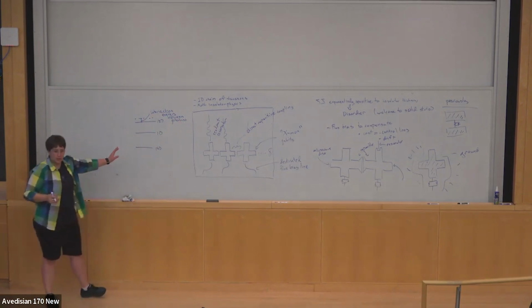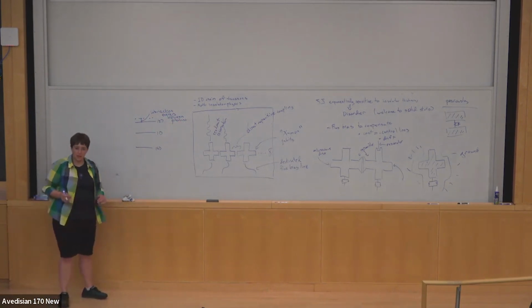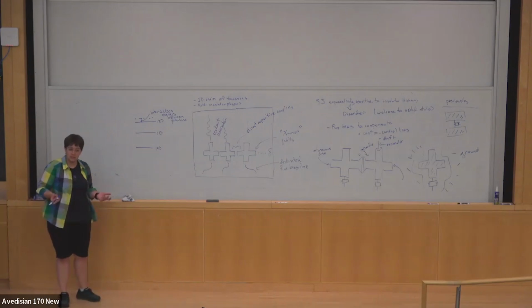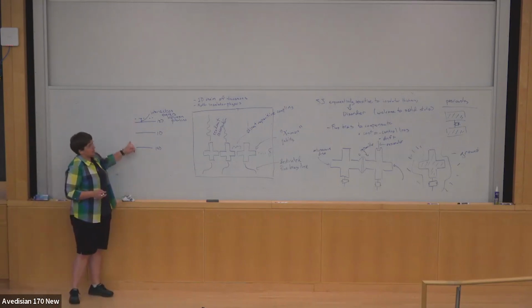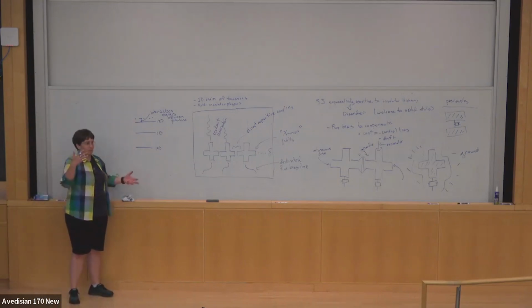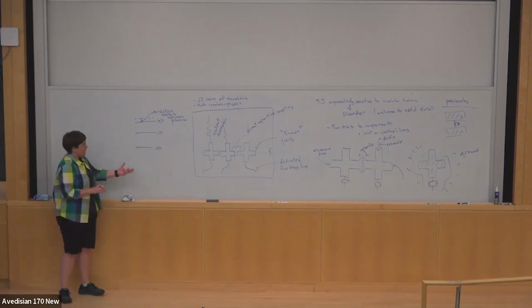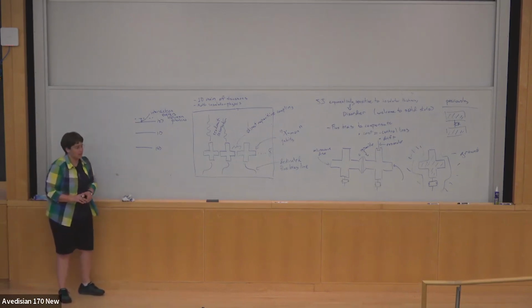You put one photon into this transmon and it's at 5 gigahertz. To put the next photon in, you need to go in at 4.8. And so you can actually think of the transmon as being a fake electron with a strong attractive interaction. It's a box for electrons with a strong attractive interaction.